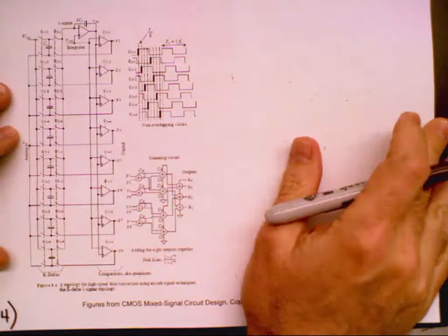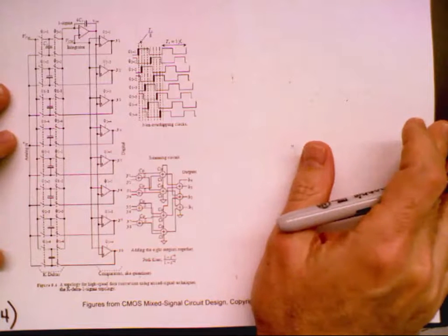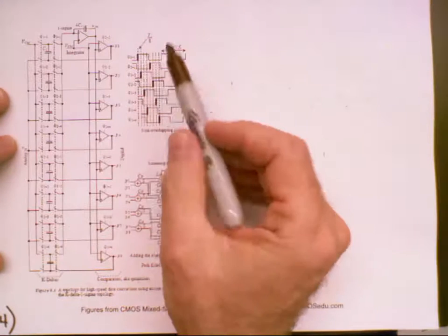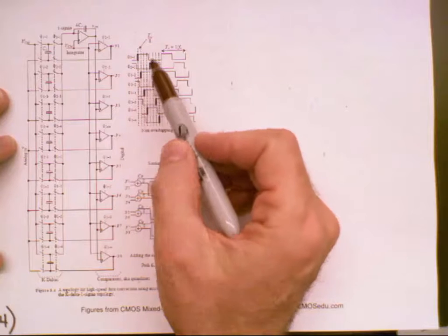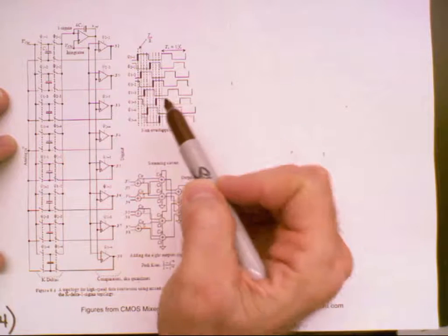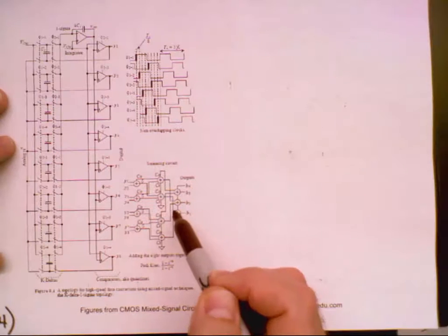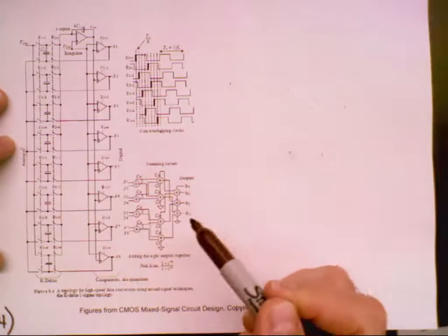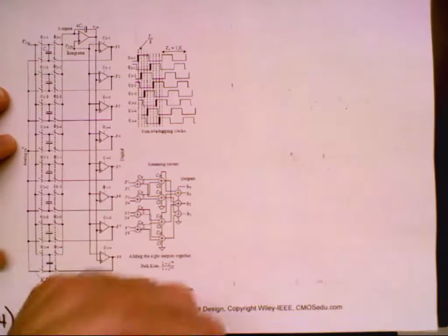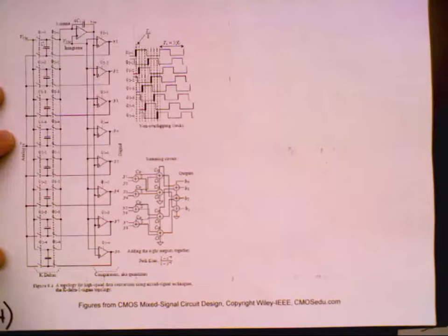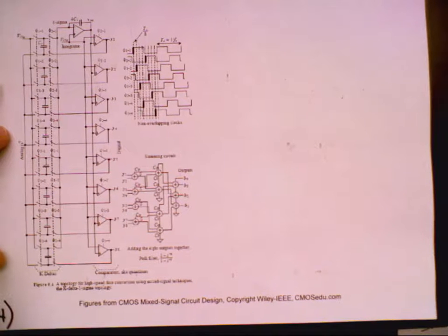All right, so here's the switch capacitor version. Now notice one thing different is that the clock phases are now non-overlapping. Here is an output filter. Here's one thing I definitely want you to be able to answer. In the MATLAB script, what's the difference between serial mode and parallel mode? Why do you get higher signal to noise ratio in serial mode rather than parallel mode?